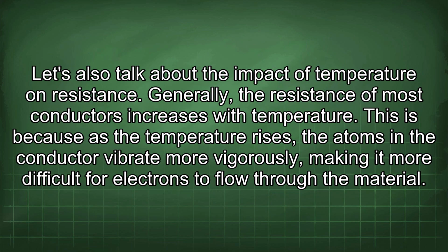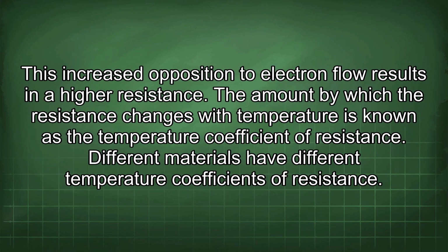Let's also talk about the impact of temperature on resistance. Generally, the resistance of most conductors increases with temperature. This is because as the temperature rises, the atoms in the conductor vibrate more vigorously, making it more difficult for electrons to flow through the material. This increased opposition to electron flow results in a higher resistance. The amount by which the resistance changes with temperature is known as the temperature coefficient of resistance.